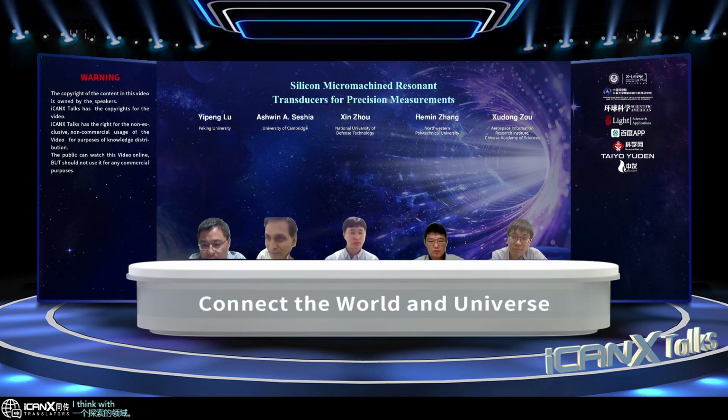I think with piezoelectric materials, there are very significant benefits in terms of integration, which is now pretty standard, and the very high electromechanical coupling compared to capacitive transduction in just plain silicon structures. And there is a different space for that, where you're not really pushing, for example, Qs. So in filter applications, that's not the primary driver, and you get adequate Qs there. And really, there are other metrics that are driving that sort of research.